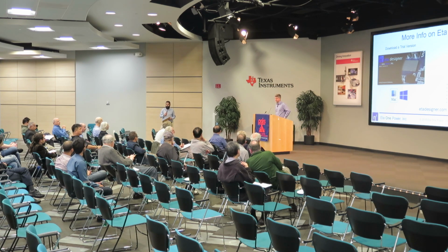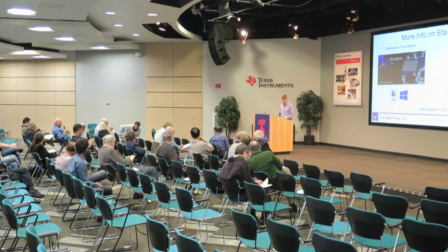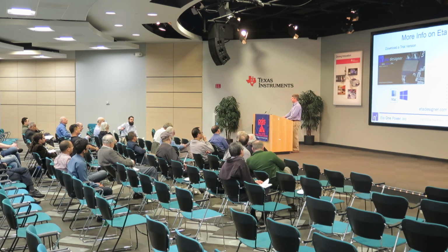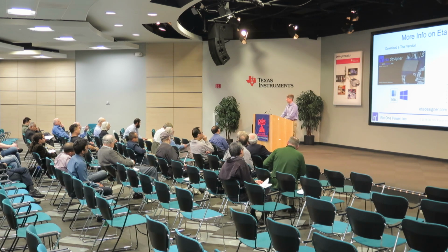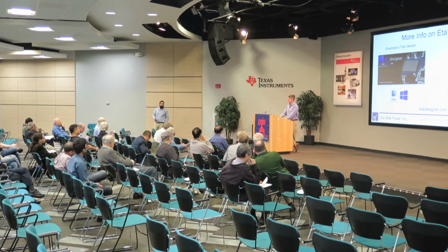Let's start with some questions. A number of the magnetic losses are somewhat dependent on temperature. So how do you handle knowing what temperature your component's going to be? Certainly your eddy current losses are highly dependent on that, but even hysteresis loss is somewhat dependent on temperature. Yeah, so certainly many of the core material-related losses are related to temperature. I haven't yet incorporated that into the model. That's definitely on the to-do list.